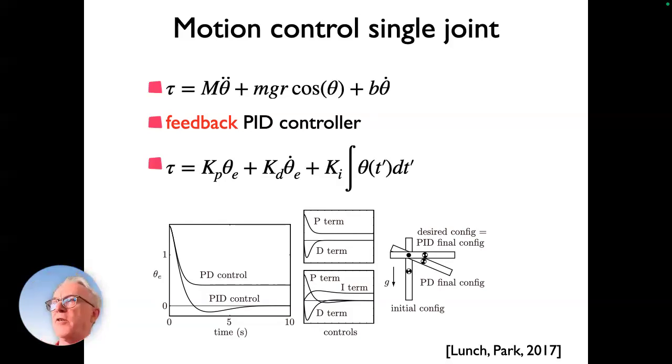So it will use as much force as it has to achieve the goal. So it's very dangerous if you have a systematic error that cannot really be overcome, and this will try to overcome it. And so the integral term is to be used with caution. In fact, you could think this was a mistake.